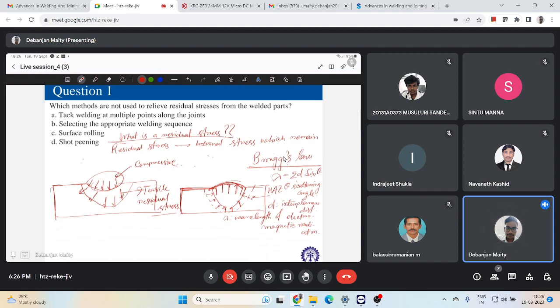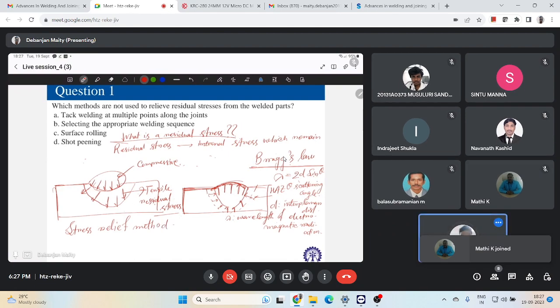or there is something called contour method, slitting section method. I'm not going into the methods per se, but the basic principle of this measurement of residual stress is the stress relief method. And these methods are used if the measurements are limited to only one point of the structure, which can be repaired very easily, right?